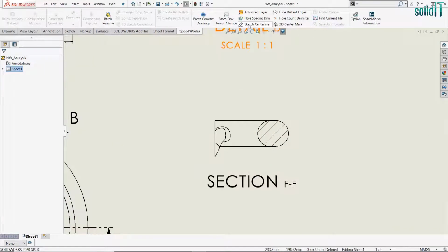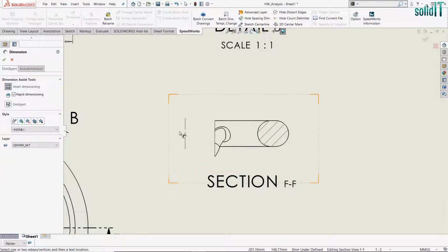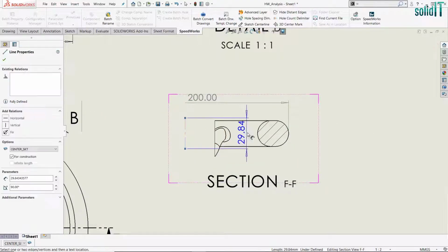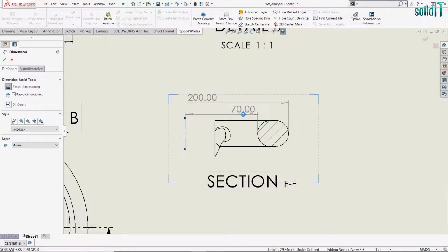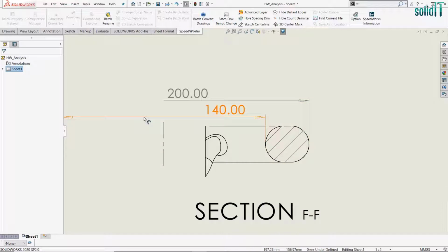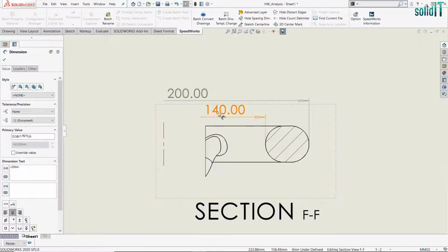It is difficult to create a centerline when only a fraction of the model is shown in the views, like section view, detailed view, etc. But you can easily create a centerline in any view, as we've mentioned earlier, by using the Sketch Centerline tool. The function helps you to create a centerline if you just select a revolving edge and symmetric diameter dimensions.